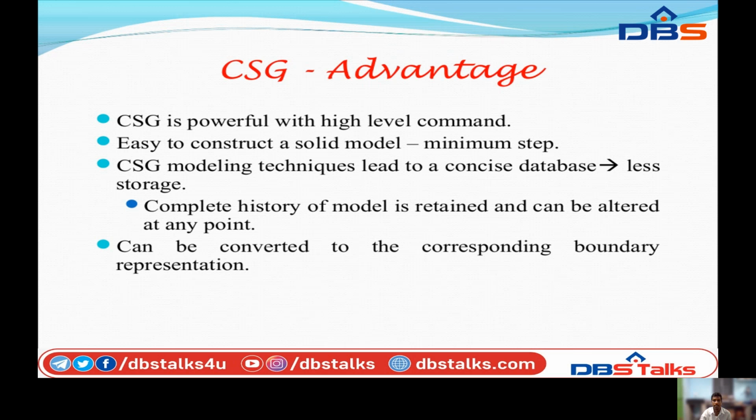Next, advantages of using constructive solid geometry. CSG is a powerful tool with high-level commands. Next, it is easy to construct a solid model with a minimum of steps. It is a very easy modeling approach among solid modeling techniques. Here, the complete history of the model is retained and can be altered at any point.